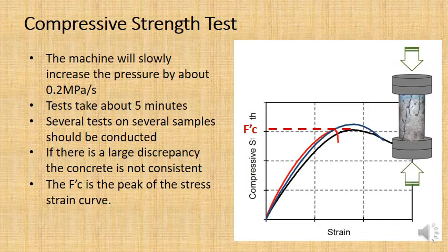We talked a little bit about this when we did aggregates, but you're looking at if the sample is 100 millimeters in height and you squeeze it, and it changes the height down to 99 millimeters, well, that's going to be a 1% strain, or a 0.01 strain. It's usually given as that, and there's no unit, because strain, of course, is a ratio.